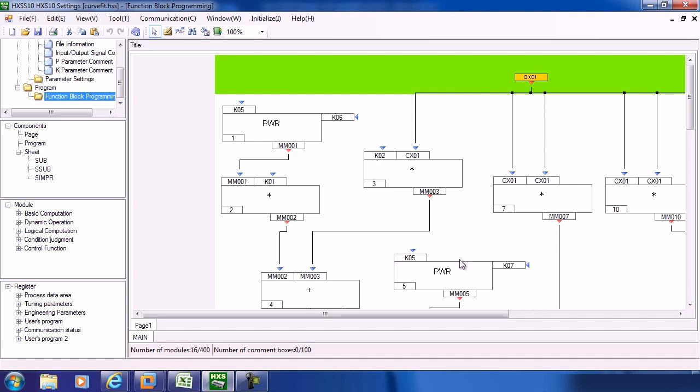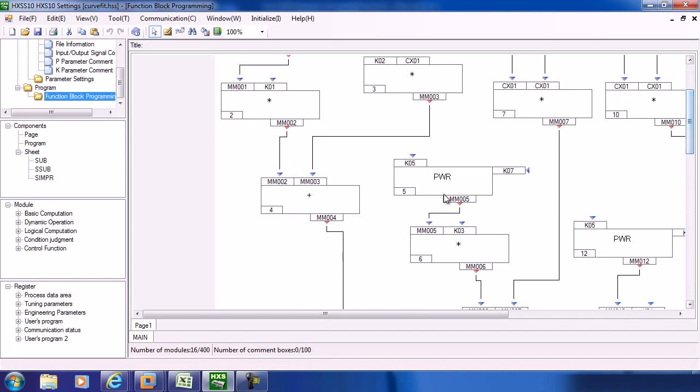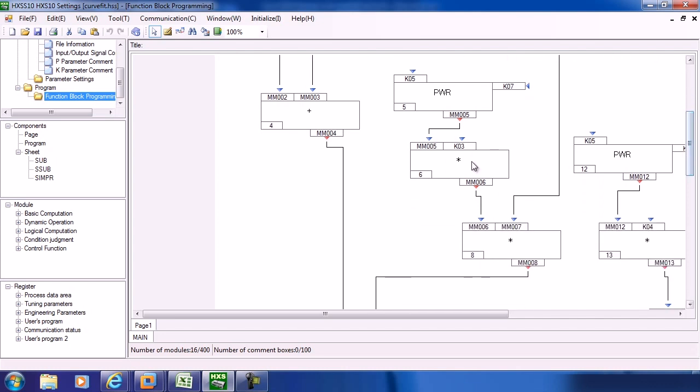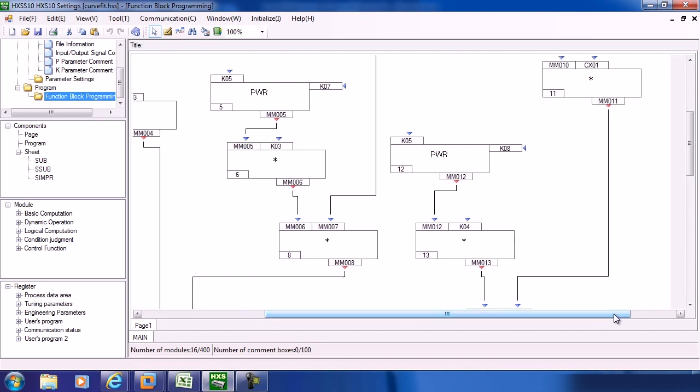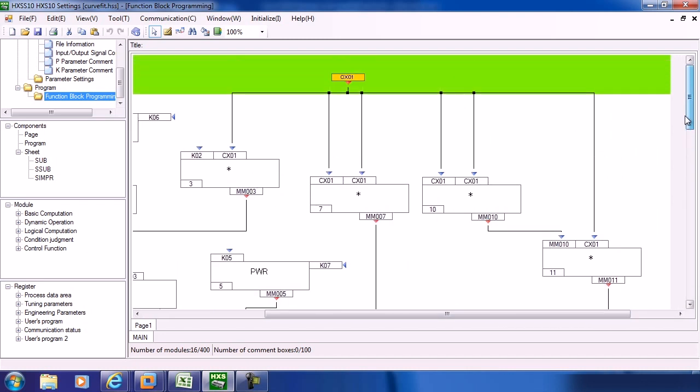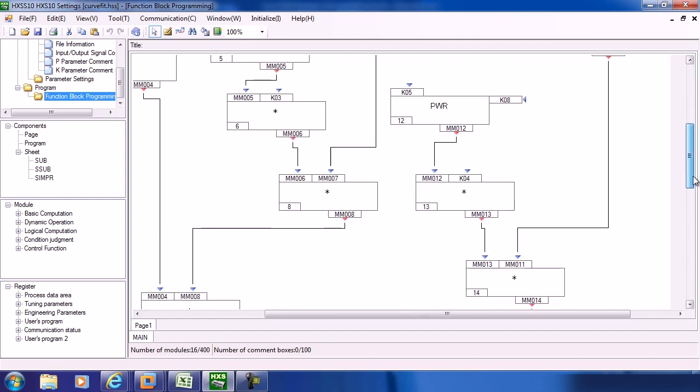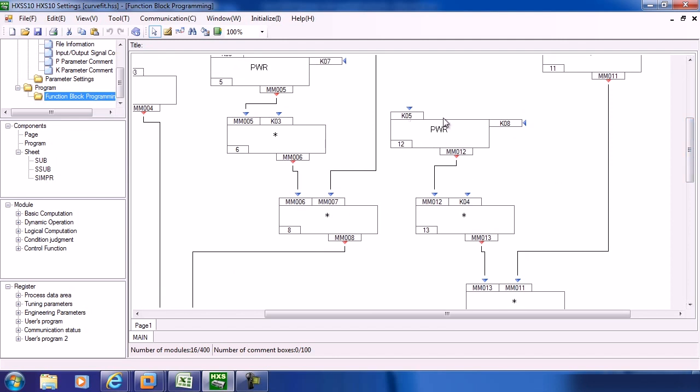And then here's the CX squared. You can see I'm multiplying X to get X squared, and then there's the coefficient being multiplied out. That's 10 to the power of -5 in this case, multiplied by the C coefficient, and finally multiplied by X squared, which is the inclinometer reading squared. Once again, I'm doing this for X cubed. There I'm creating my X cubed, and there's my coefficient. I'm going 10 to the power of -7 multiplied by my D coefficient.